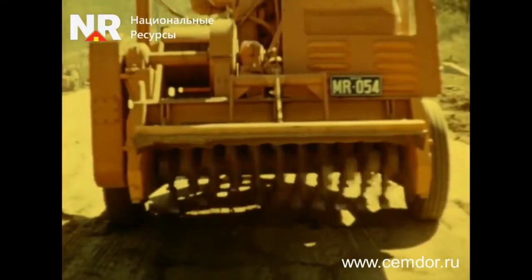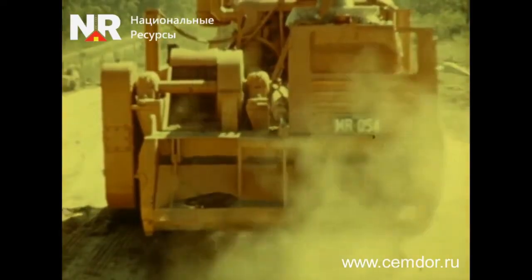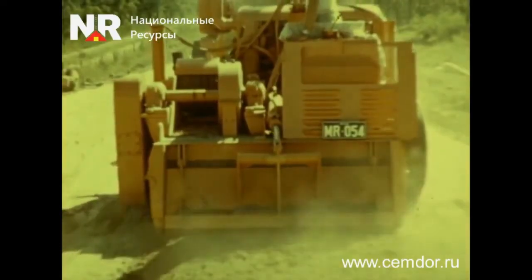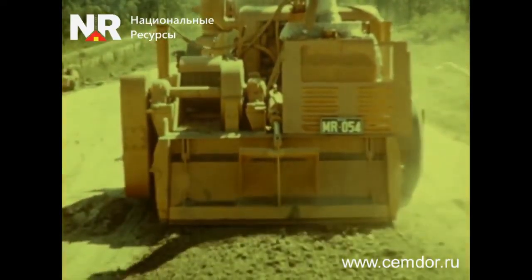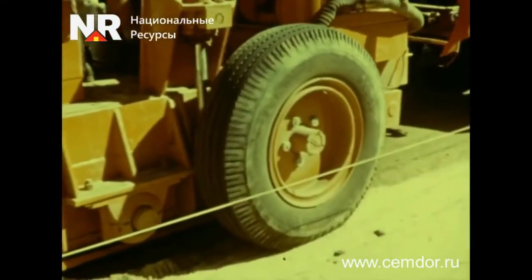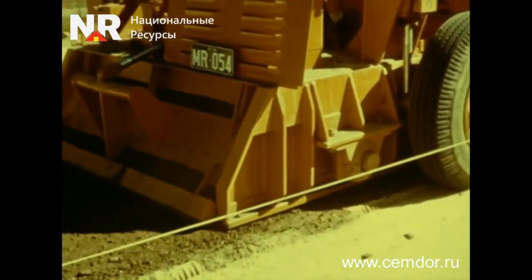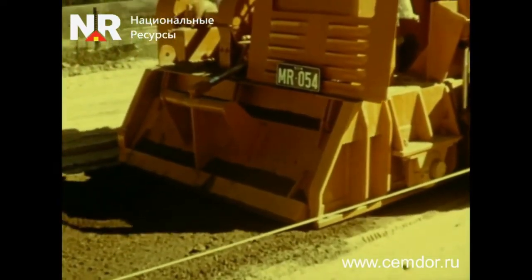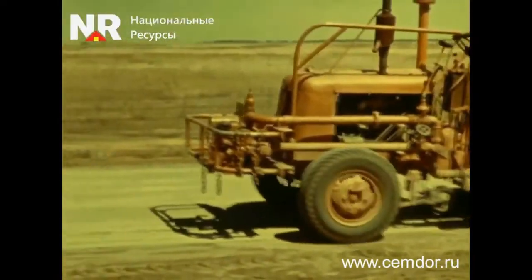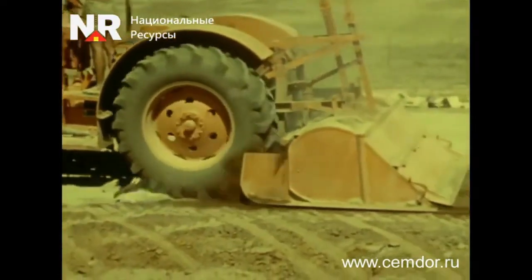In addition to the PH company's mixing machine, other stabilization equipment with a high-speed rotor is also used for loosening, crushing the soil and mixing. It mixes the soil with cement. Water for the mixture is supplied from a tank that moves ahead of the mixing machine. A road milling machine is another rotary machine designed for multiple passes over the road surface.